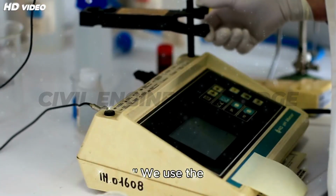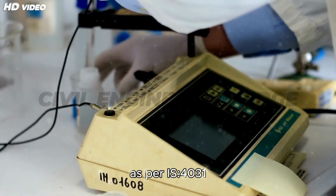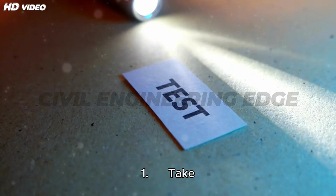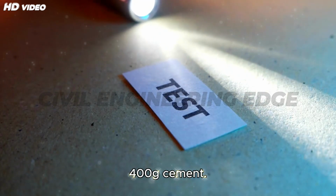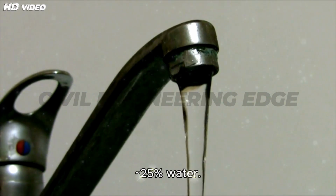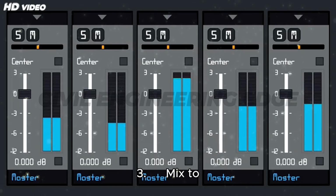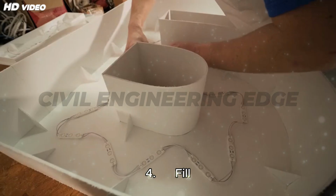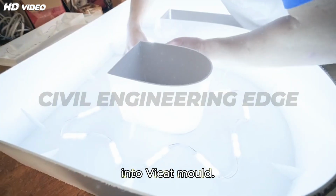We use the Vicat apparatus as per IS 4031 Part 4. Test procedure: 1. Take 400 grams cement. 2. Add approximately 25% water. 3. Mix to paste form in 3 to 5 minutes. 4. Fill into Vicat mold.